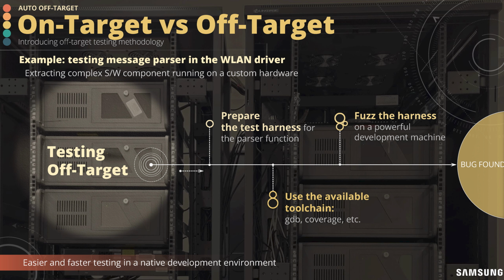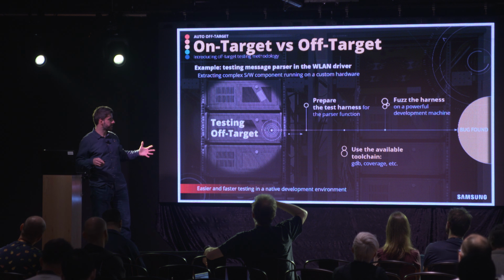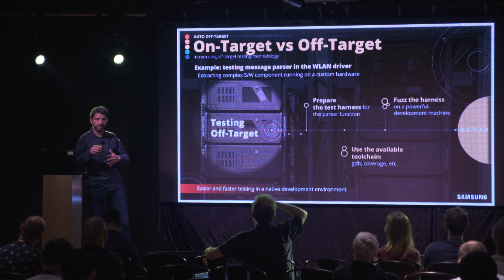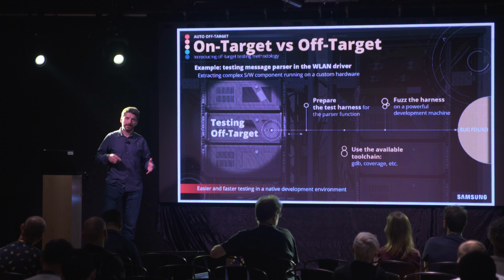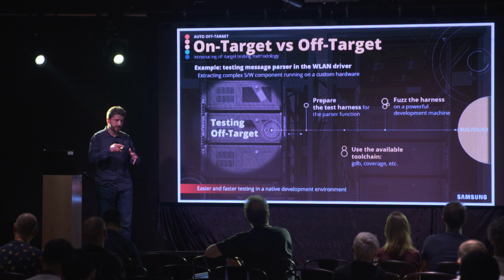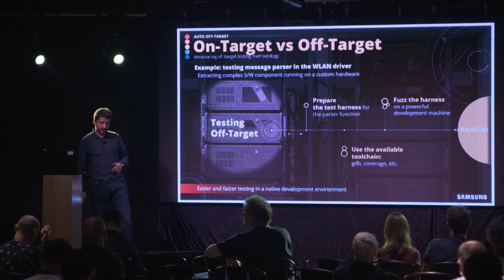In that setting, you would have access to all the tools available on your development machine, right? You could use GDB, you could embed coverage information, you could use fuzzers, sanitizers, Valgrind, even symbolic execution is possible in that case. Of course, I assume that the parser doesn't depend on the hardware very much, so it's just portable C code that shuffles around data between buffers and doesn't write to the CPU registers directly.